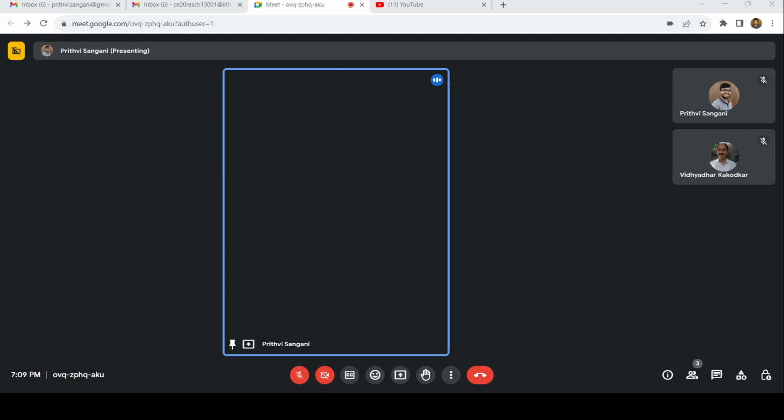This thing is kind of direct. So this is 1 kilonewton. There is no force in this, and if this is 1, this should be 1. So this happens to be, if this is 1, this is also 1. So do we have any vertical forces coming anywhere in this beam in the virtual? I mean, on the truss with the virtual load or the unit load, there are no vertical forces coming, right? So there are no forces in these members.